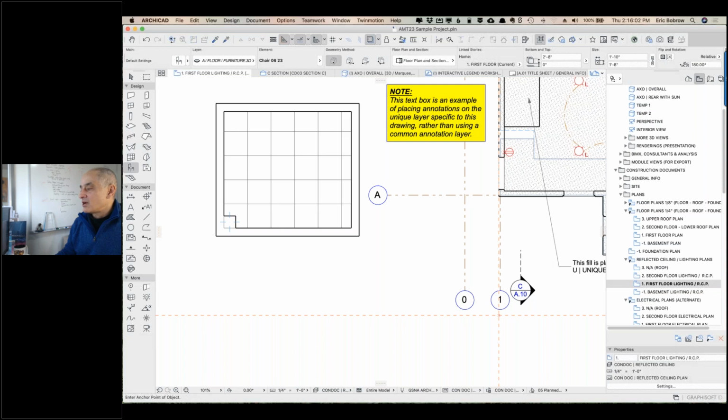And Tom says on layouts when typing directly on a layout. So yes, in a layout, if you think about it, for the most part, whatever you put on a layout, you want to show all the time. So in general, when you put drawings on a layout, each element, whether it's a drawing or some annotation or even parts of the title block, they do have layers. And in general, we would say put everything on the ARCHICAD layer, because when you open up a layout sheet, you just want to have it all there and print it.